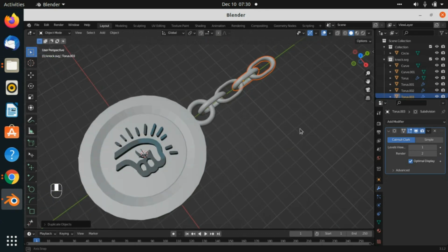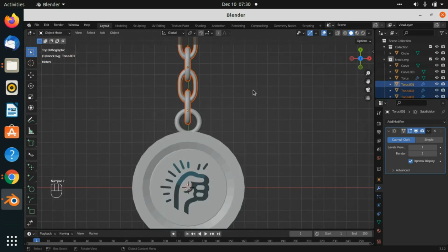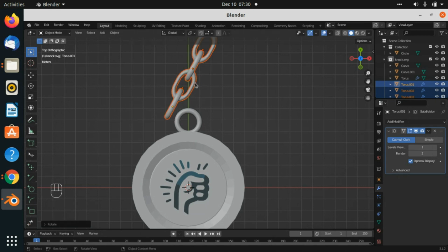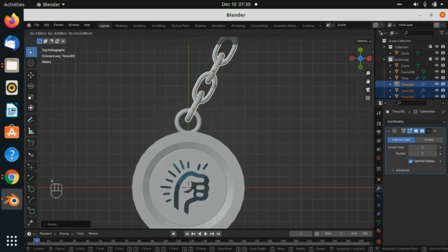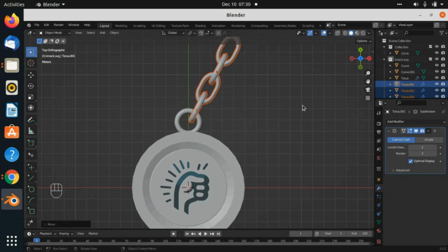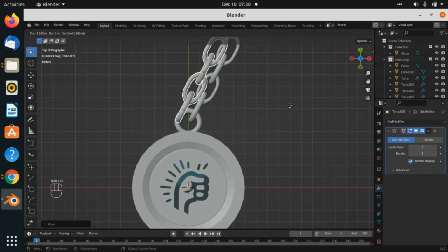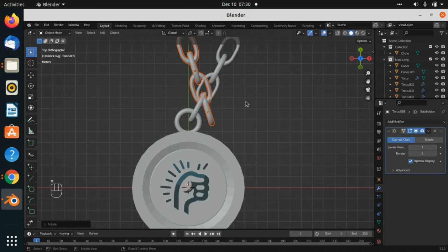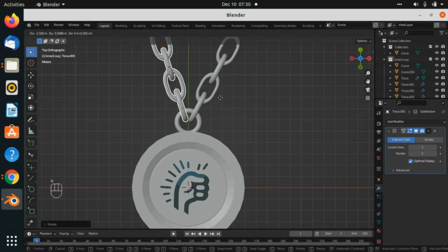But you can see the chain is being developed already, which means I'll probably need to make this rotate so that I can, let me rotate it around like this, then grab it along X axis like this. So this will be duplicated also, but rotated so that it can now join the hook there.